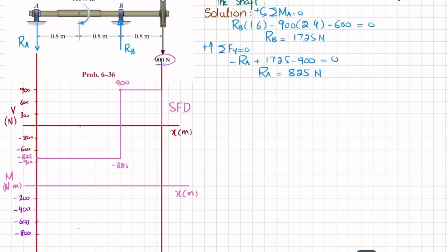So we look at minus 660, and this is the point. And you can see that the shear force is a horizontal line with 0 degree, so the bending moment will be one degree higher, and it will be a straight line with a slope. At this point we have moment equal to 0 because x is equal to 0. Now you can see you have a clockwise moment which is 600. While drawing it on the bending moment diagram, it will be taken as positive due to convention. So minus 660 plus 600 will be minus 60.